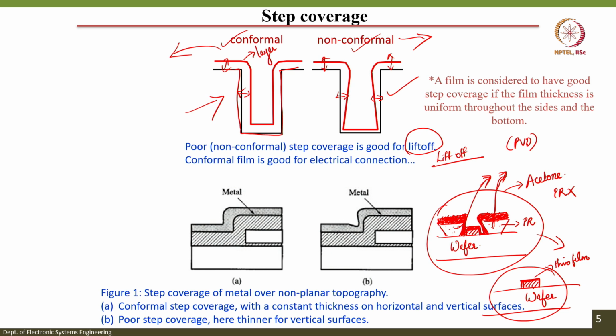For example, if you are planning to fabricate a sensor or a particular device, you will first of all set the entire process flow that is required to realize your device, and based on that process flow, whether you are adopting a lift-off technique or a normal lithography and thin film deposition technique, the choice of the deposition techniques would vary.